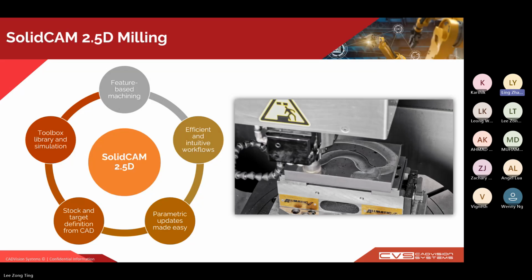And stock and target definition from CAD. So why is this important? Basically, SolidCAM uses your SolidWorks model to define both your stock, which is your raw material, and your target, which is your finished model. No need for any external geometry.